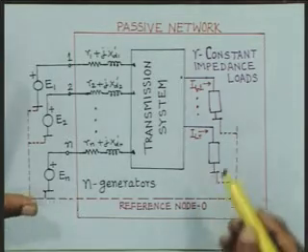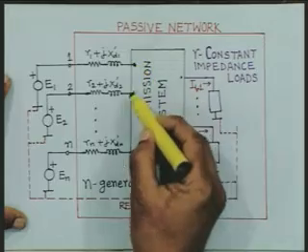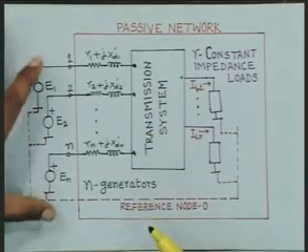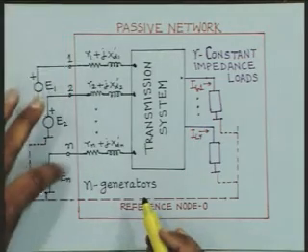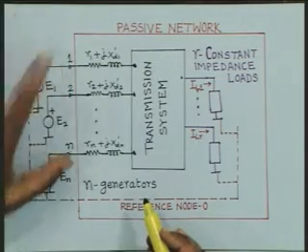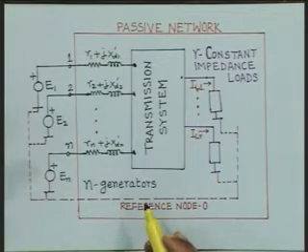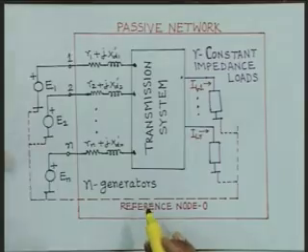All the load buses you eliminated, and the buses where these generators are connected are also eliminated because there is no injection there also. But ultimately, you will get a model which has the n nodes where the generators are connected and these are the constant voltages, that is, voltages of constant magnitude. Their phase angles will vary during the dynamic conditions.